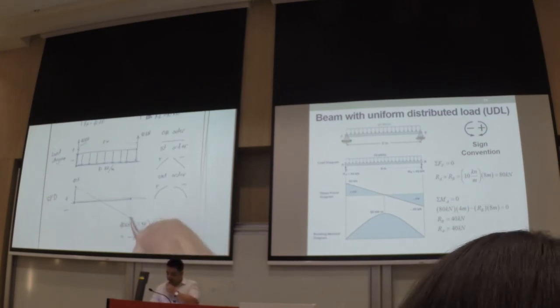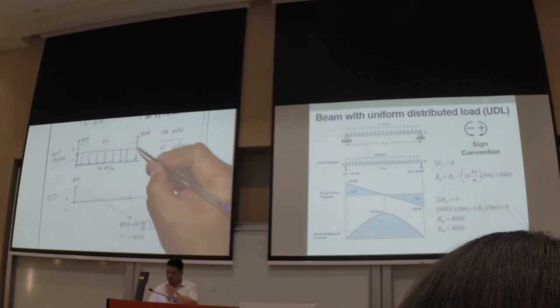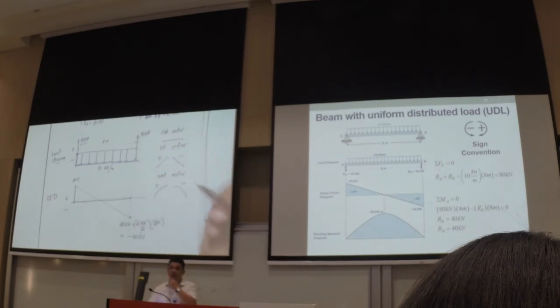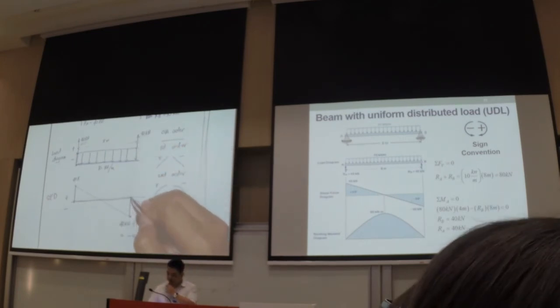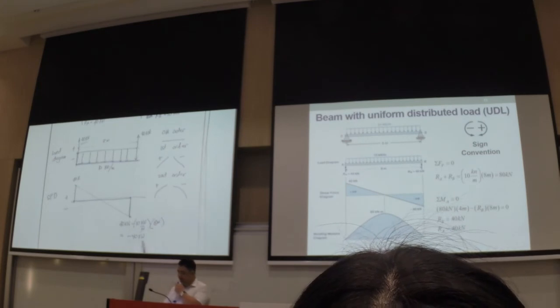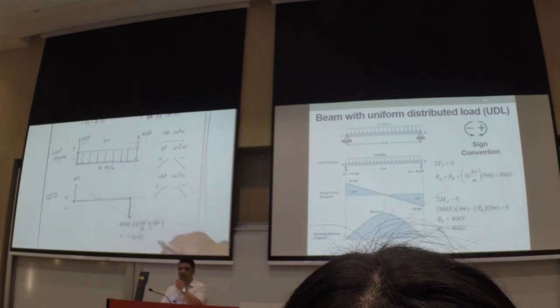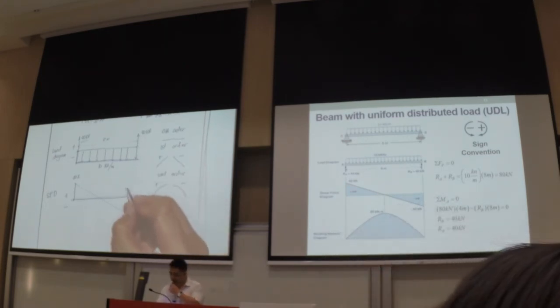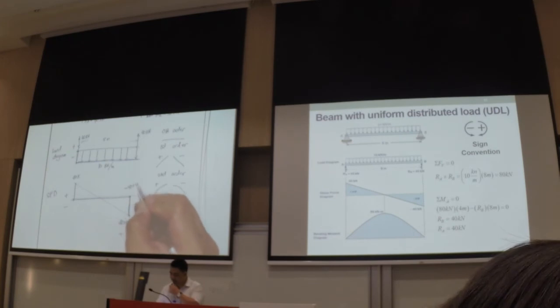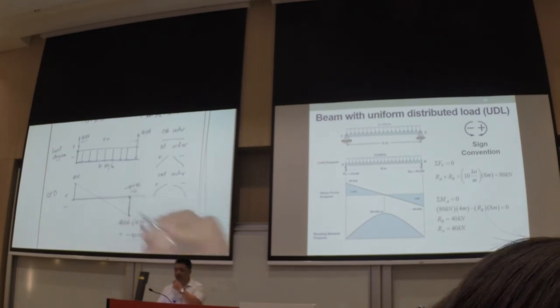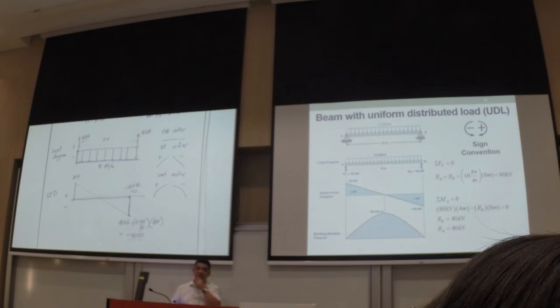Now we have this one to be negative 40 kilonewtons, and then we have this one here, 40 kilonewtons going up, so we simply go up. And we know that negative 40 plus 40 will be 0. So we stop at 0. So that's one way of checking it.